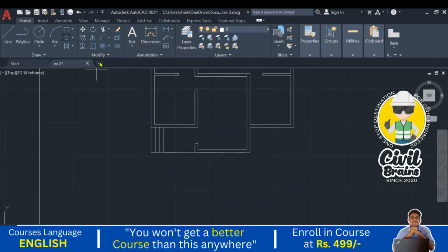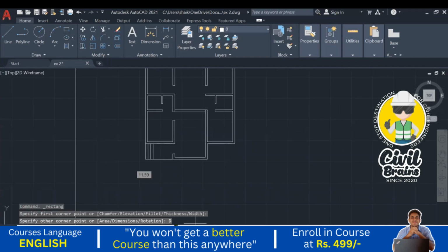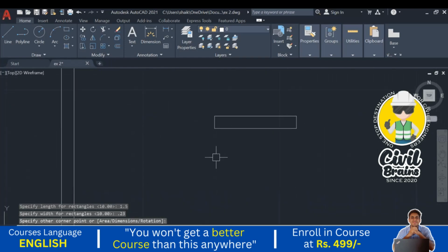Okay, so we just go to the rectangle. I will prepare the window. So I just provide the dimensions. What are the dimensions? 1.5 meter width. Enter. What is the thickness? The depth of the window is equal to the thickness of the wall. If you see it from the top, the width and the height, the depth is different. Whatever the thickness of the wall is, that is 0.23. Enter.